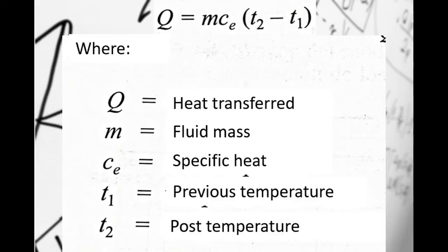When the fluid is at rest, the temperature is identical in the two probes. And when it circulates, it carries a quantity of heat to the second probe, and the temperature difference that increases progressively occurs in both probes as the flow rate passes. The difference is proportional to the mass that circulates through the tube, according to this equation.